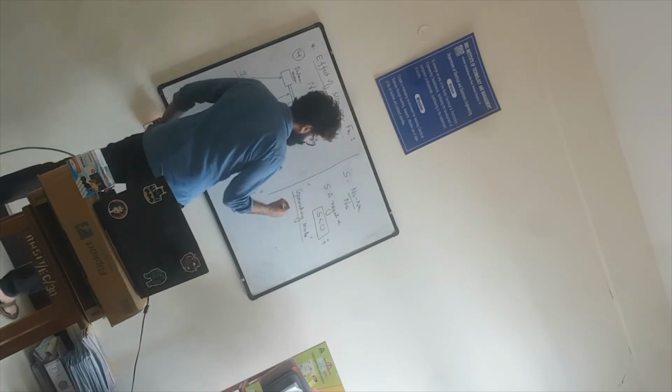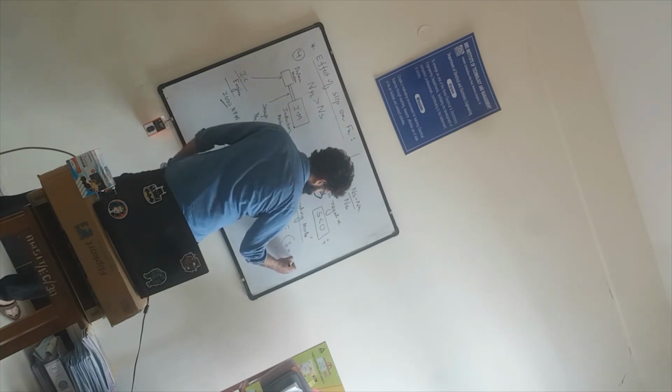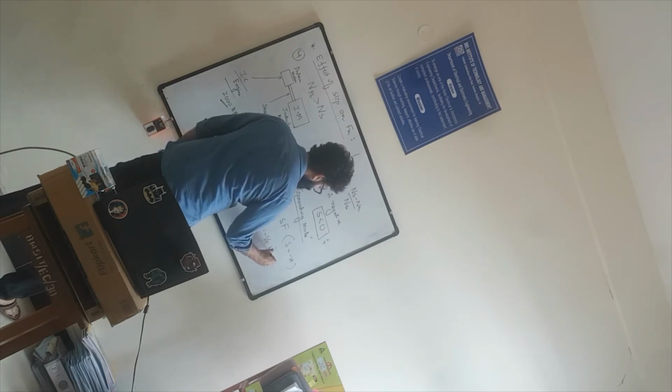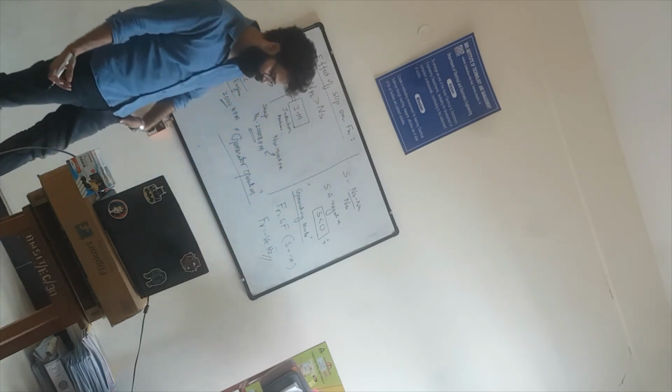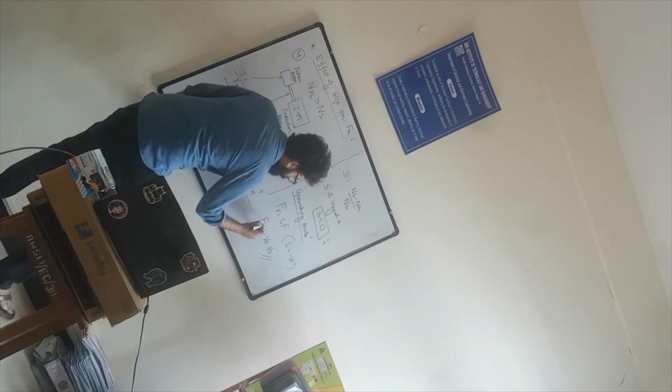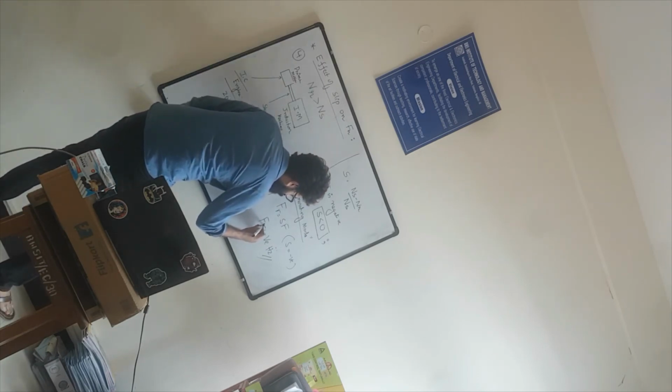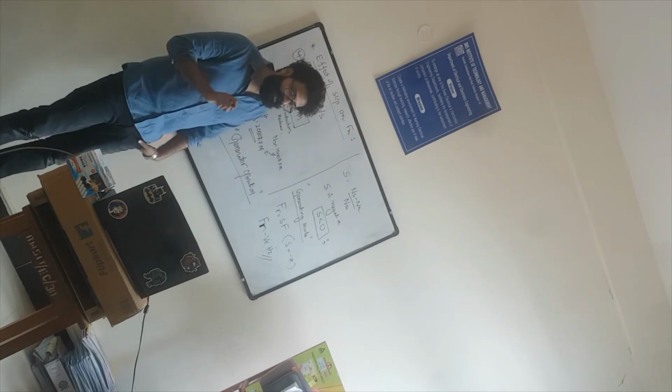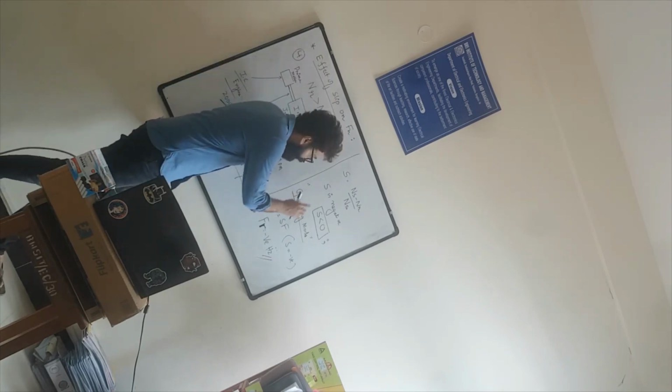So when slip is negative, what happens to Fr? Fr is S times F. As S is negative, you will get Fr equal to negative hertz. But frequency we always consider as a scalar quantity, right? 50 hertz, 60 hertz. We never say minus 50 hertz or plus or minus 100 hertz. So same thing over here also. The negative slip value is a mere indication of the power reversal.